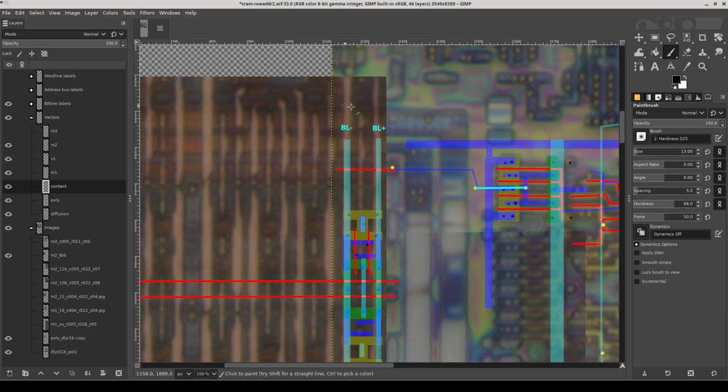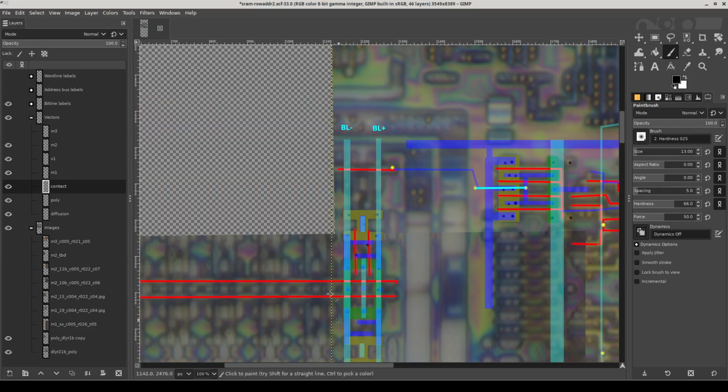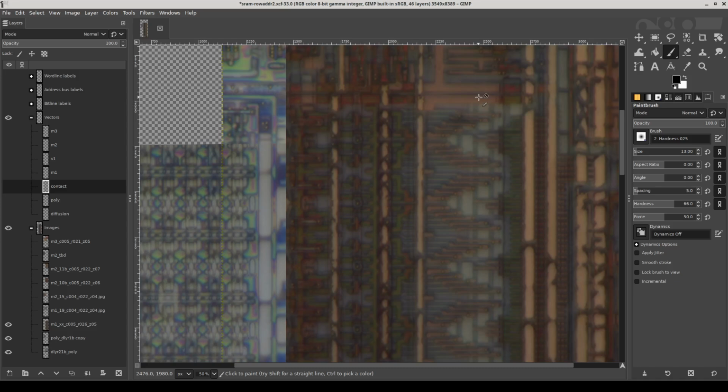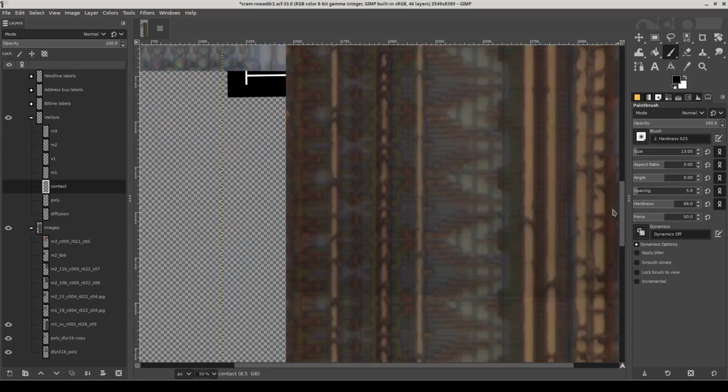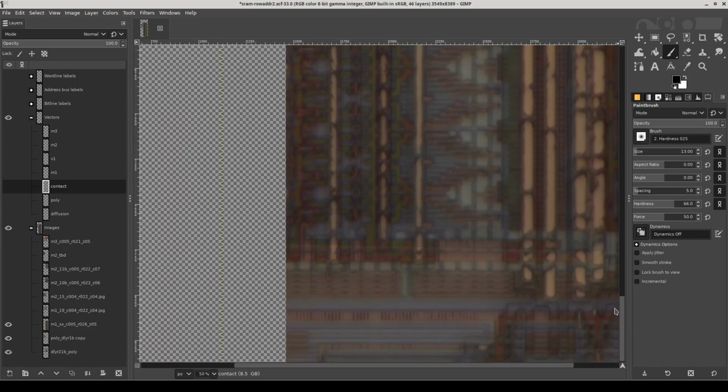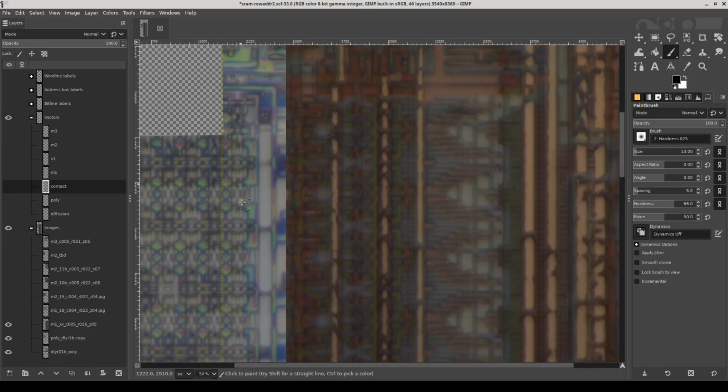So we're just going to stop the analysis at the bit lines and then shift our focus over to where the word line comes from. So now we're up to about the metal 1 layer. There's some partially etched metal 2, but mostly metal 1. And we can see that there's this repetitive looking pattern here running all the way down the entire height of the memory array, which I don't have in all of the other images because it was all the same. But in this part, if we look closely, we'll see it's actually not quite the same.